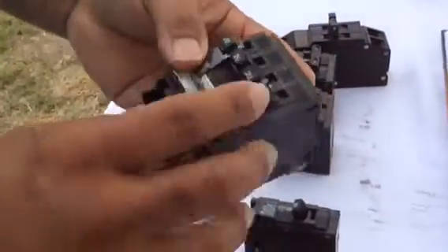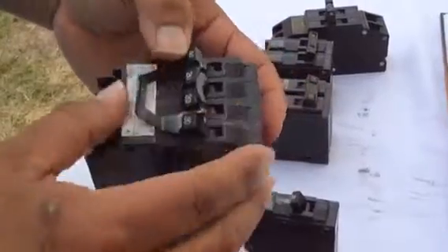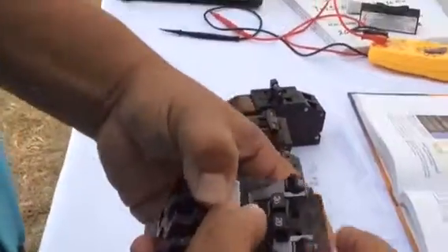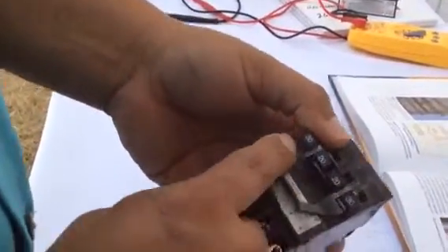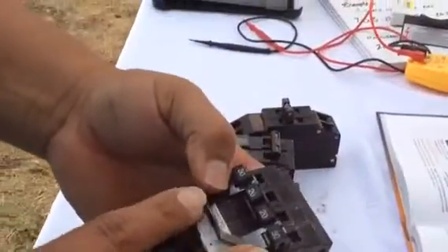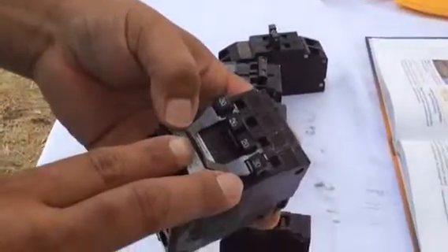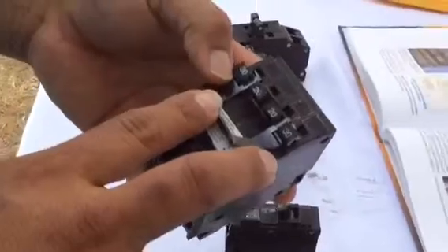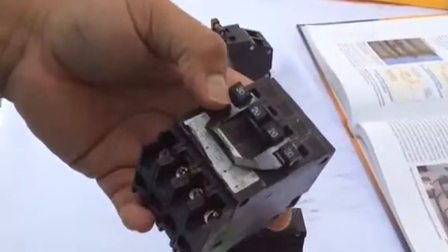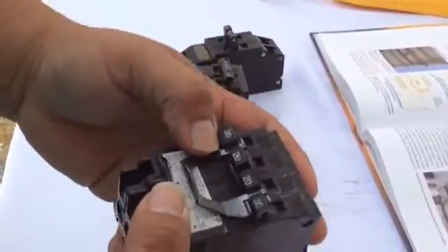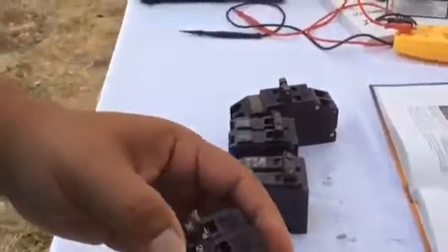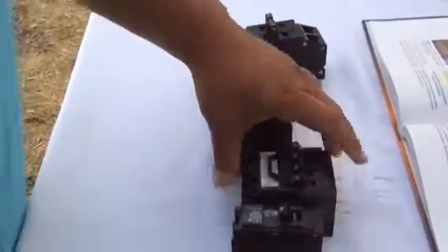Here we have a quad where we have these 30 amps on the outside, and as you can see, they're linked by this. This is for things like your electric dryer, your air conditioning systems, things that use 240 volt, 220 volts. Here's a 20 amp. What's nice about these is that they save space within the electrical panel. So these are a lifesaver sometimes.